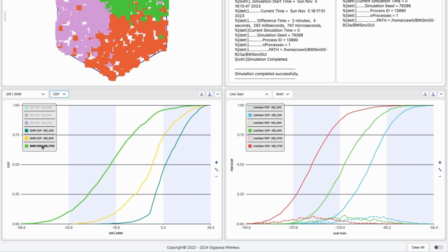And this is where I would like you to take a deep look into the equation where the numerator is signal power and the denominator is interference power plus noise power. While yes, the effect of interference power is less pronounced when we move to a larger ISD, so is the impact of signal power. Imagine users in a larger cell, the users who are far away from the base station experience very little signal power.